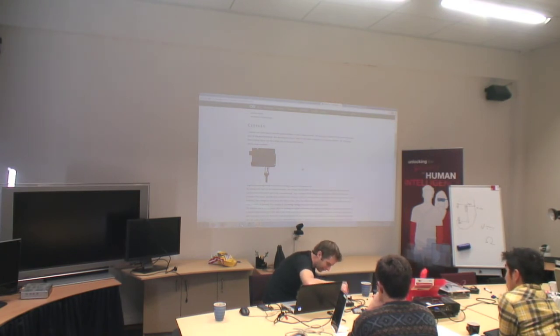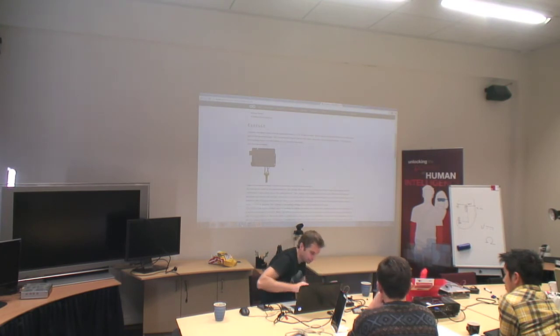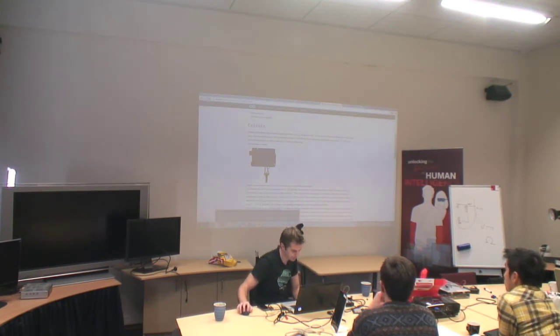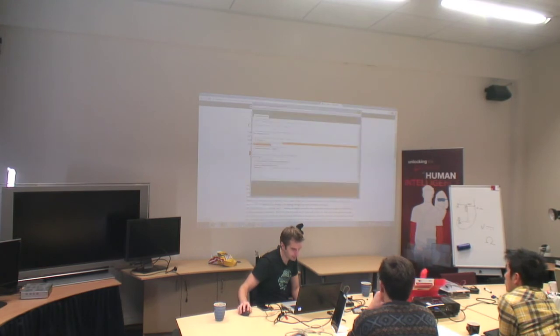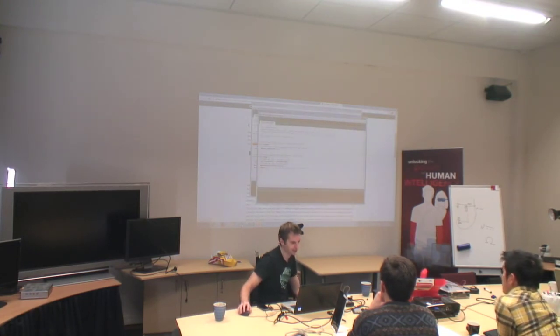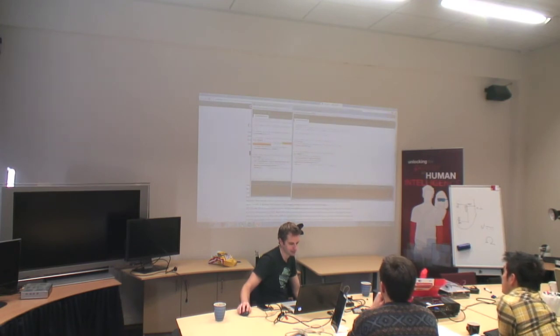And then we'll connect 5 volts to, whoops, I just short-circuited it. 5 volts to one, and ground to the other, and we'll put the sense pin in the middle. And let's jump into File, Examples, Basics, AnalogReadSerial. So this one is pretty much the same as the other one if you look.